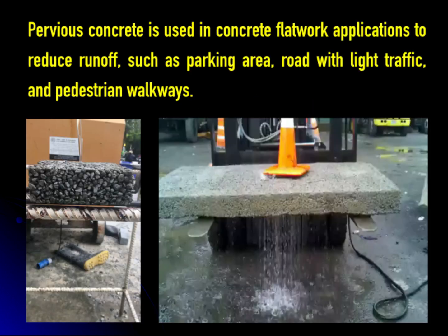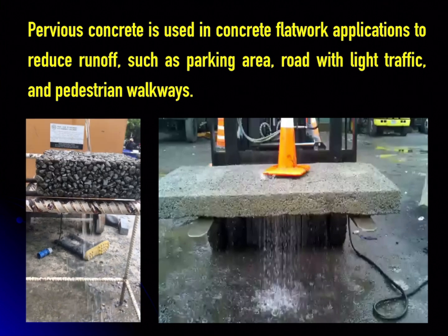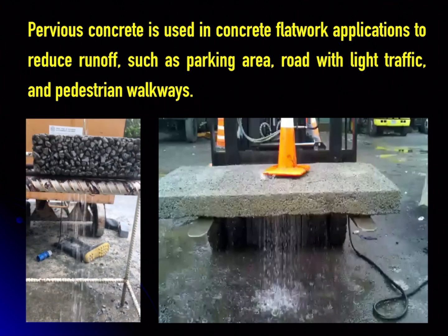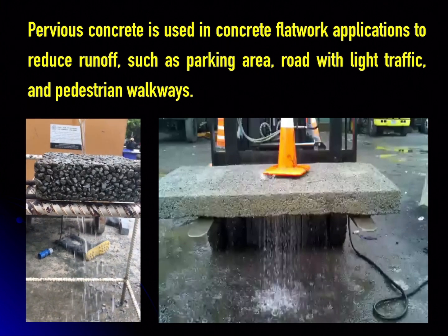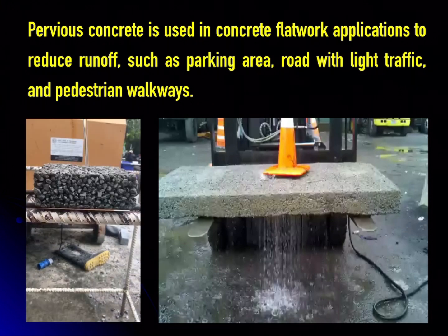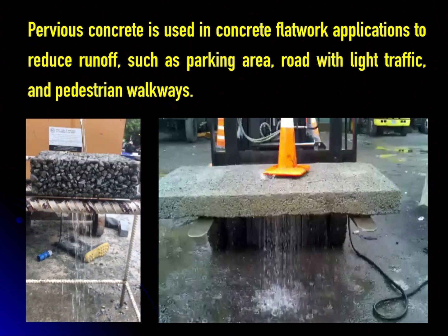The picture and video clip show porous concrete developed at the KMUTT Concrete Laboratory. This mix has a compressive strength of about 40 megapascal and a water flow rate of approximately 1 liter per second, which are enough for use as urban road pavement.